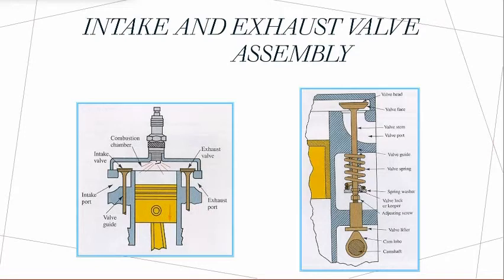Both inlet and exhaust ports are shaped to curve upwards and outwards, emerging from one or both sides of the cylinder head. It is normal to have one inlet and one exhaust valve and port per cylinder. However, twin inlet and exhaust valve and port layouts are also adopted for some high-performance or large-capacity engines. Also, a few engines use twin inlets but only one exhaust valve.